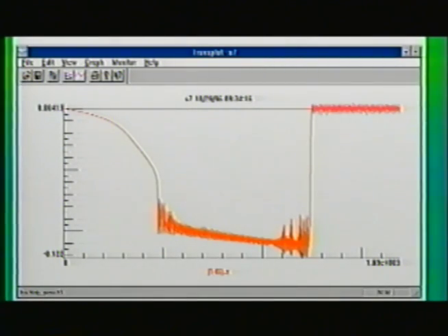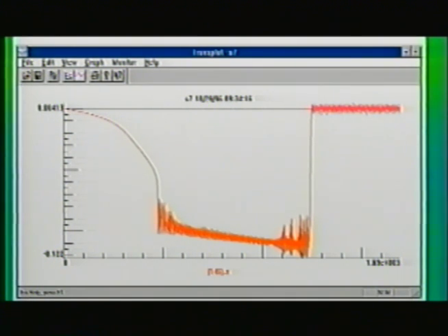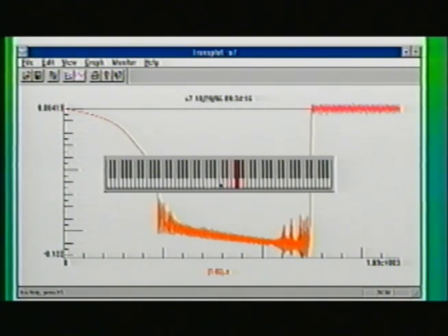The sound or pitch of the snap-through agrees with the frequency shown on the plot. It occurs at 198 cycles per second or hertz and corresponds to the note G below middle C. The pitch of the snapback is somewhat higher with a frequency of 396 hertz, or the note G above middle C.